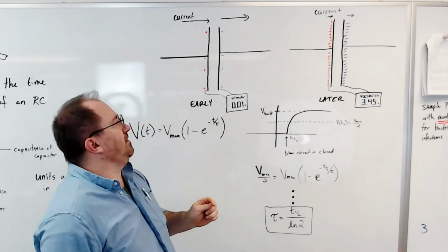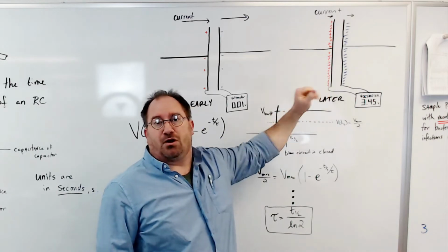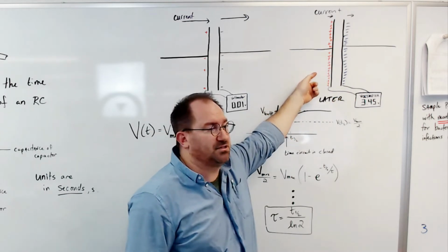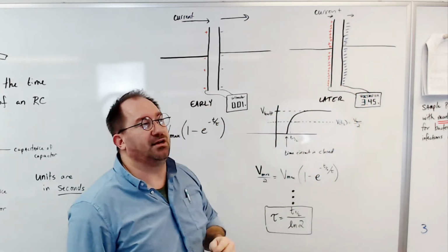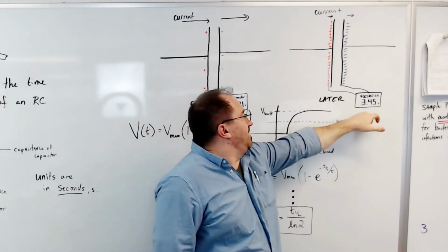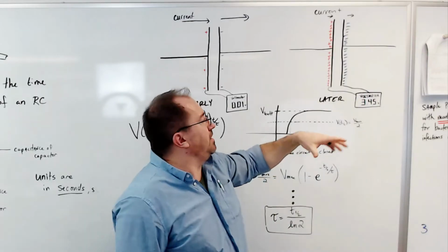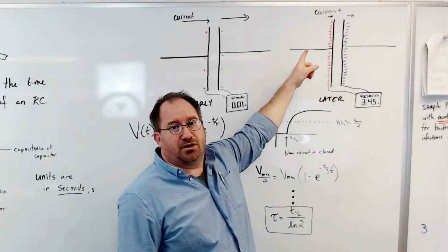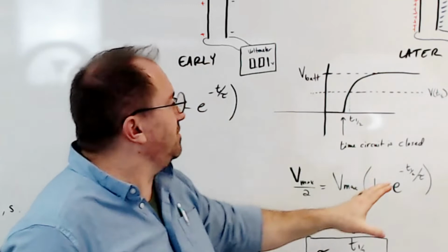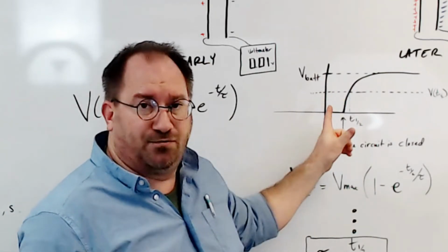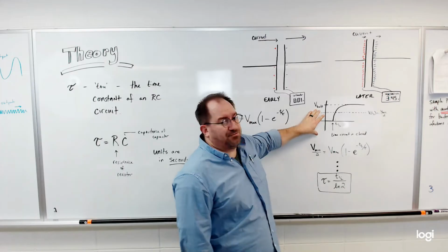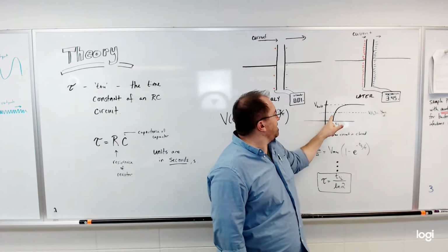But as time goes on, they get really crowded. It becomes harder and harder for charge to move into the space because there's been a charge buildup. Positive charges repel on the positive side, and negative charges repel on the negative side. As a result, there's a voltage difference between these two sides that is higher than it was before. And this results in a drop in the current, the flow rate of the charges in the circuit. Eventually, over time, the voltage reaches some maximum value, whatever you've applied to the circuit, and it follows a curve.